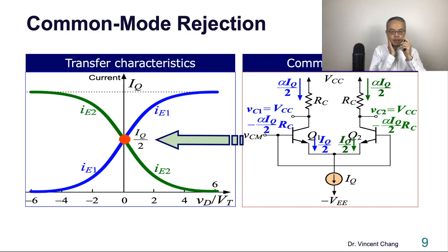So you have the common mode, right? If we just imagine this, if we put VCM equals 1 volt, here's the result. Then you change VCM from 1 volt to 2 volt, the result is the same. 2 volt to 3 volt, same. And 3 to 2, same. 2 to -1, as long as the transistors are biased in the active region, the result won't change.